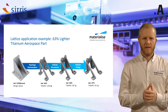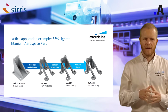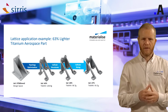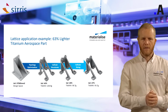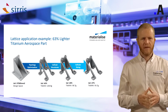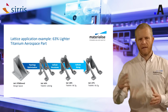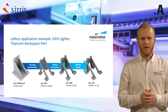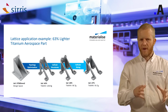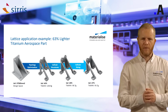Within this design space, a topology optimization is applied to get to an initial design. The topology optimization cannot be done in Chromatic software, so for that you need another software. But then we can start from this topologically optimized part and apply lattice structures to make the part even lighter, and also in some areas to avoid putting supports for printing.